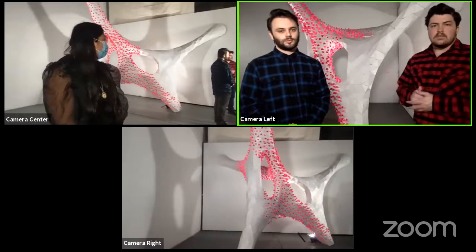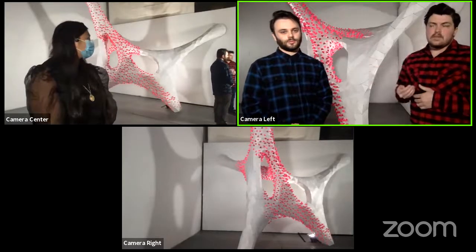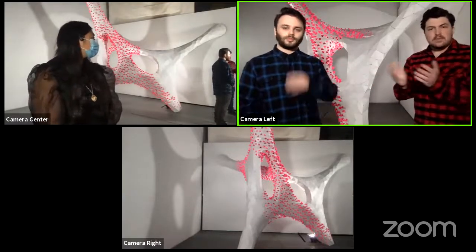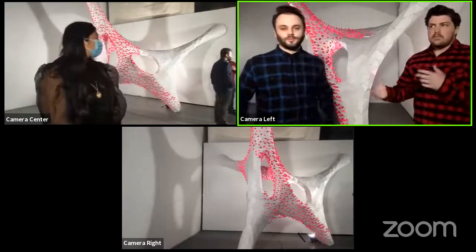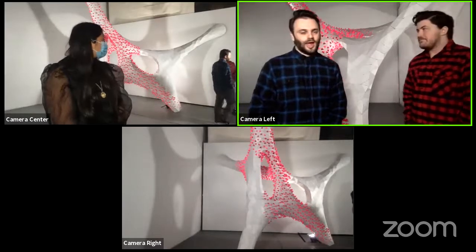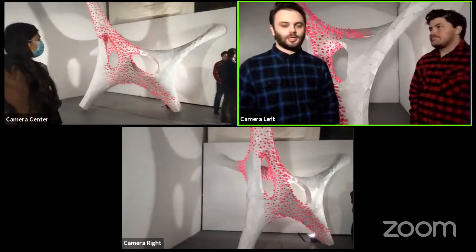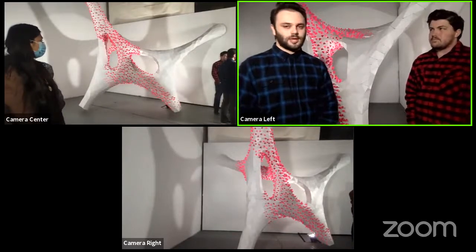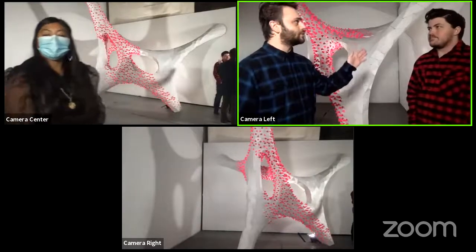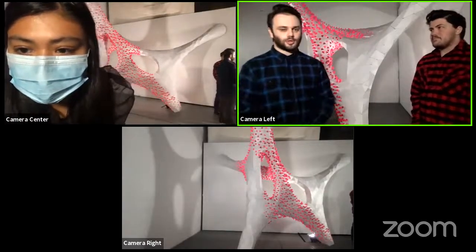We could certainly use CNC to mill some of these other types of materials. And then you could get a V-groove drill bit, if you're familiar with CNC, to get some of those angles and those pivot points. But the laser cutter worked great with the scale of the material we were working with. For an analogous process for a stiffer material, you could use a plasma cutter or water jet to cut aluminum sheeting, and that would fold up much the same. There would only have to be some considerations for the thickness of the material, which were mostly negligible with the paper, although aluminum would be a little bit thicker, but completely possible for the same type of construction system.